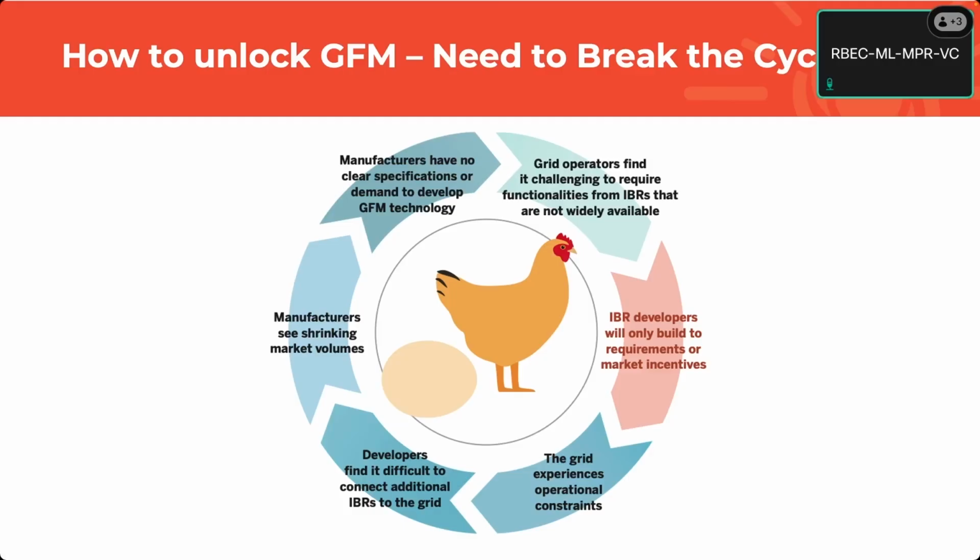I don't totally agree with this sort of spectrum idea of grid forming. I feel like there is a fundamental difference between a grid forming control and a grid following control. You can blur them. You can make the grid following devices very fast. It's a little bit like if you want to make a pencil vertical, you can either hang it from your fingers and it's just going to be vertical, or you can try and balance it on its eraser and it will be vertical, but now you're going to have to work at it to make it work. And one of them's a lot easier than the other. And so that's why I kind of just feel like just make it grid forming instead of trying to make a grid following device so hyper tuned.